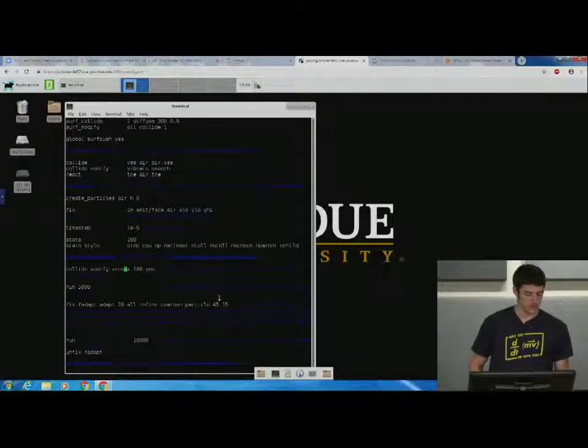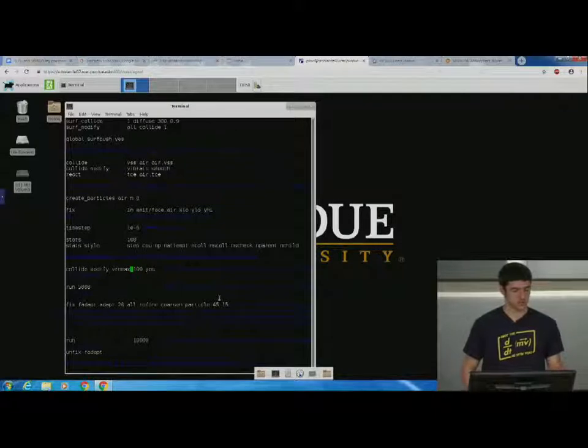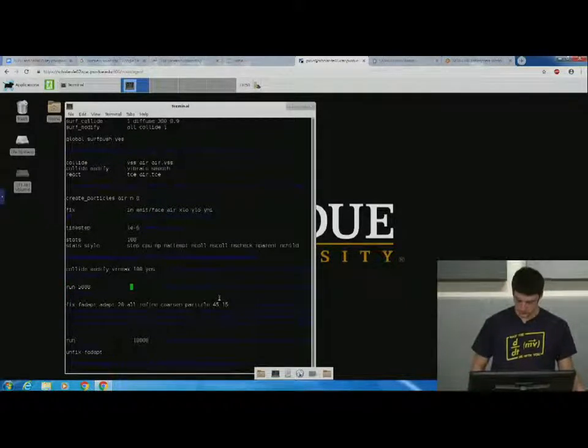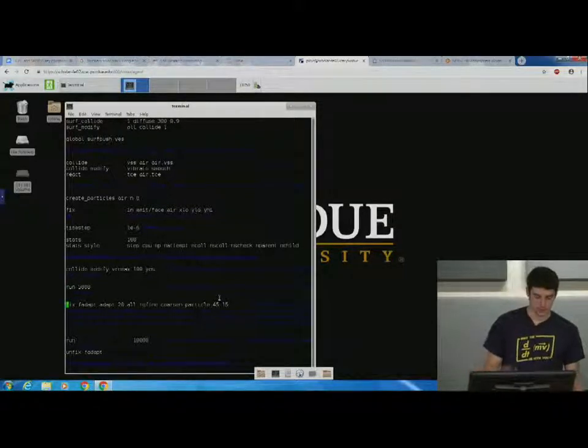So this command here, I'm not going to go too specifically into what it does, but basically for this sort of flow regime, which is still unsteady, you want to use this command. Later we'll change it to something else that's better for the steady flow. Then I'm telling it to run for 5,000 time steps. And then the next thing, and this is really dependent on your problem.